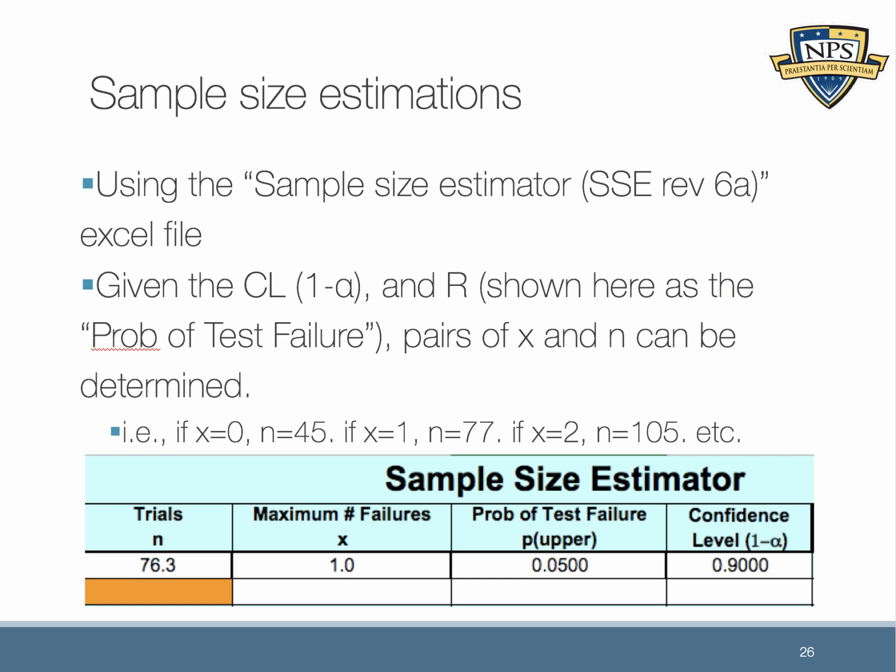But if you see a second failure at 70, now you know you need to go up to 105, right? And what you can probably already gather out of doing this is that, if in reality you were to do that, at some point you might realize, well, I actually really can't prove a reliability at 95%, right?